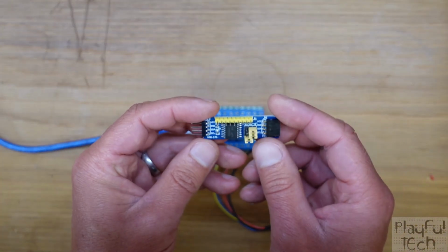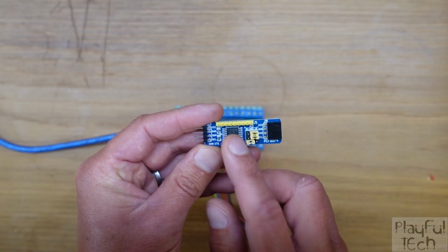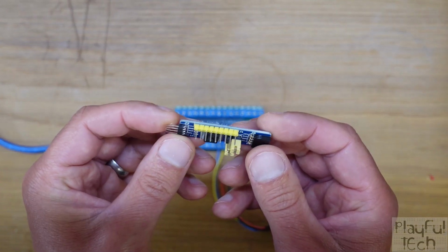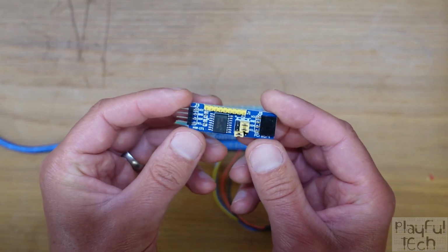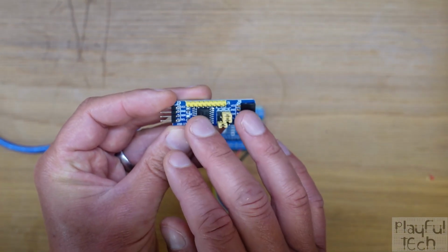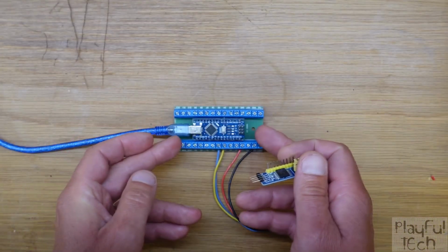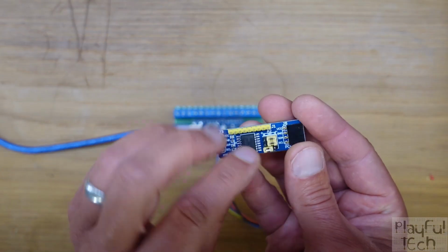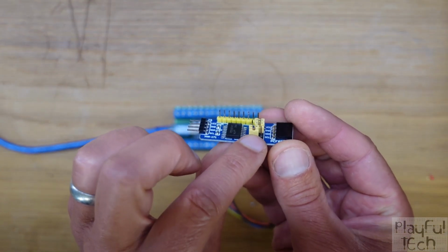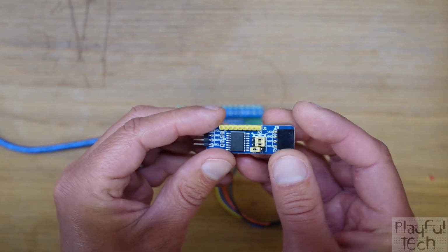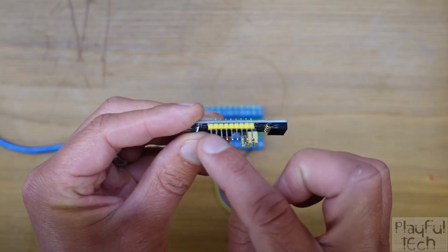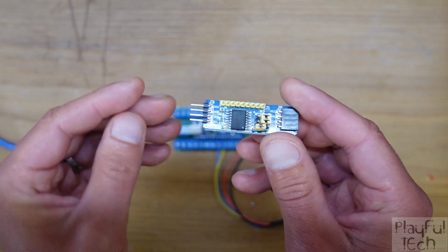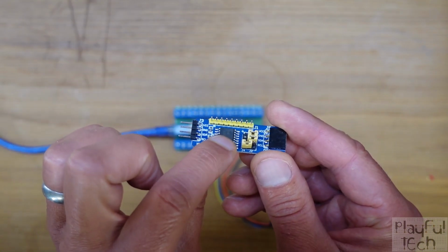Now here I've got a PCF8574 port expander. That's the chip in the middle, and it's been mounted onto a breakout board. This is an I2C device, so it communicates with the Arduino using these 2 lines. It's got some jumpers on the board here which let you assign an I2C address to the chip, and then at the top of the board it's got these 8 pins which correspond to the 8 additional GPIO ports that this chip provides.